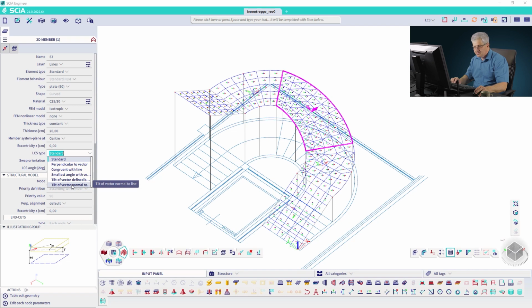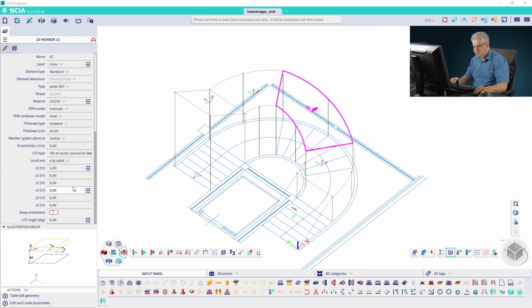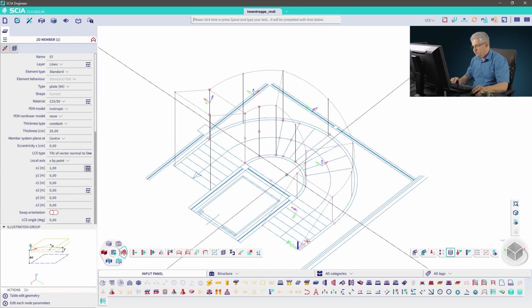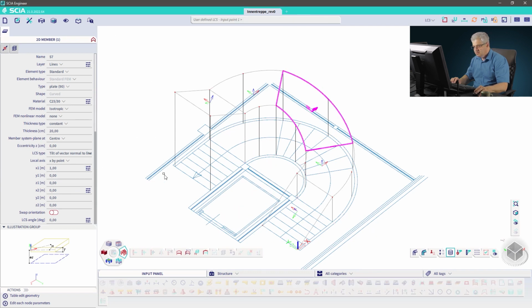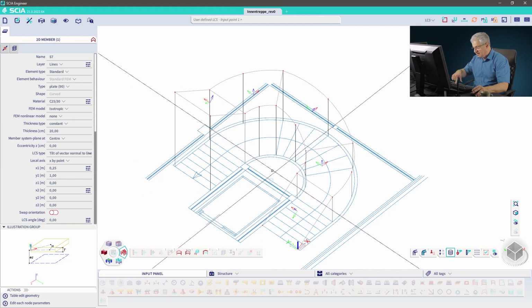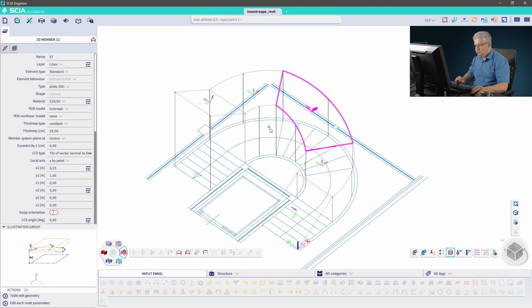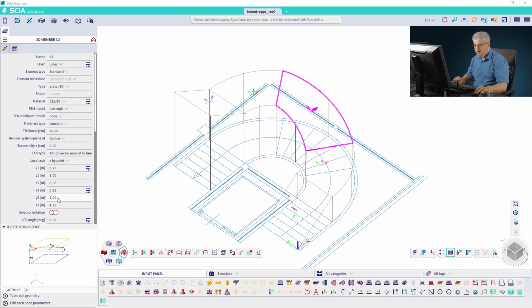You can also work in shells with the smallest angle with vector, but this is a very good position. Then you have 2 points. The first one is this center point, and the second one is from this center point. I push the shift button, move to this node, release the shift button, go to the top, for example, to this position. So now I have a line, and I would say the y axis is going to these points.